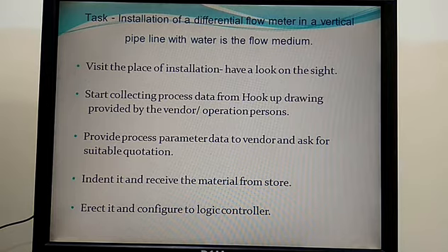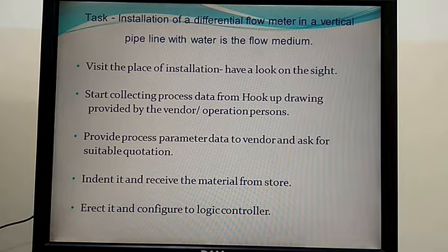If any change is there, you make the change and again give it to the vendor. And finally, when they say, sir, now go to indent. Indent means you have to give this document, you need some documentation that you are procuring these things. And after that, all official work, when you receive the material from store, go erect it and configure it to your logic controller.